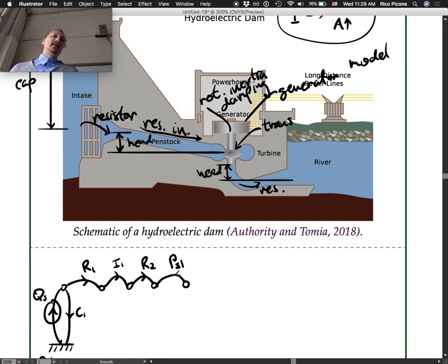The sign on this, I'm going to put that way because what that says is the pressure drops from this node to that node, which is correct, right? So the pressure is higher here than it is up here because it's at a lower elevation. So you've got your lower elevation underwater, you're going to get a higher pressure. So the pressure here is higher than it is here.